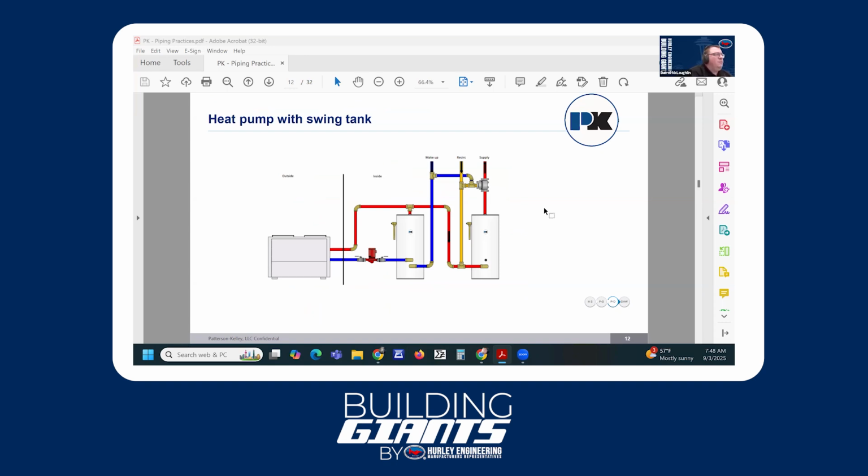What we're really trying to avoid is short cycling of our heat pump equipment. If our temperature changes are small, we don't want small changes in the temperature of our output to cause the boiler or the heat pump to come on and off. So we've got a reserve storage of heat capacity in this swing tank, so that as our temperature drops, we can serve that load with the water that's already been stored and not have to turn our heat pump on every time our temperature drops a little bit.